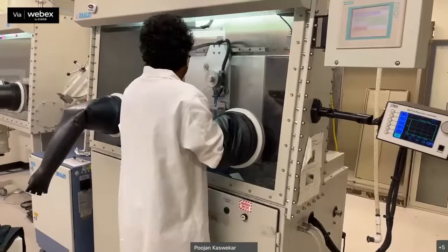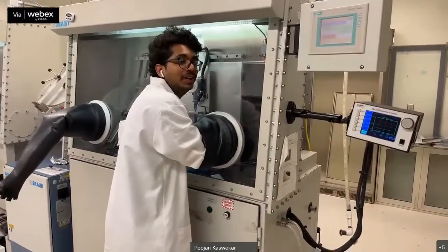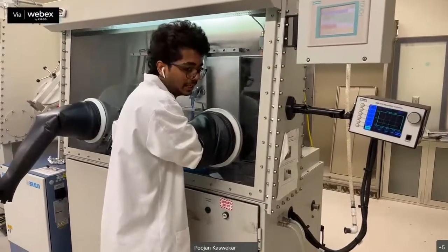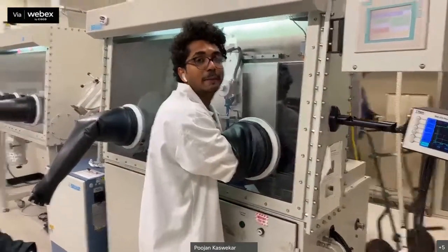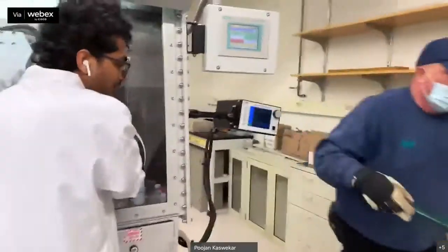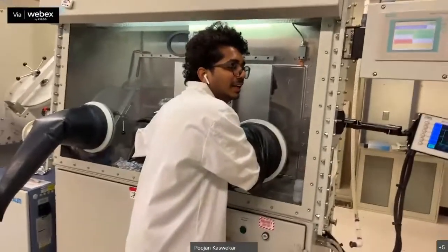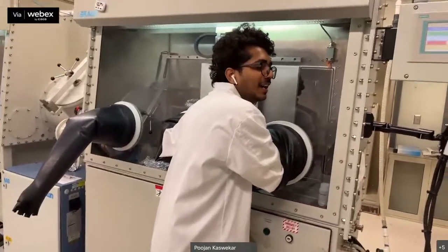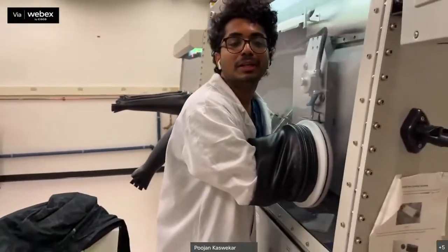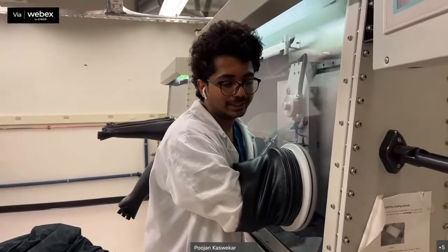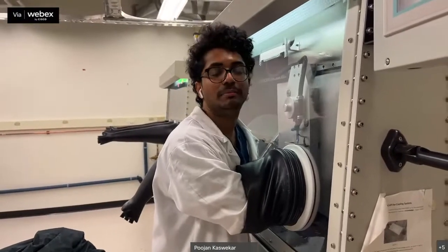Frankly speaking, aluminum is better, but we can't deposit aluminum in a particular thickness. We can't control the aluminum thickness properly in our evaporator. That's why we go for silver here. Generally, we face this problem when using aluminum as a contact: the nature is not very shiny and not very sticky, with some amorphous nature on the top. We face the same issue with aluminum too, that's why we are going for silver nowadays. As I told you, it depends from material to material, and you need to optimize a lot of things before you get a significant result.